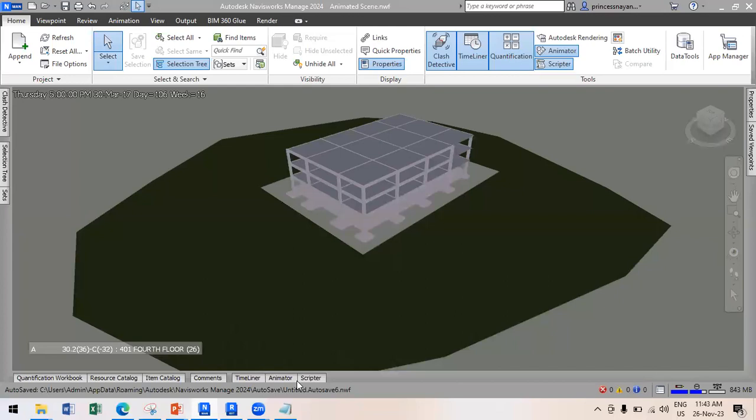The advantage is, imagine if you do any modification further, you can do one more quantification and you can see the previous and existing. It's very simple. There is a method, but first you should understand the tool. We have to create project parameters, shared parameters, because sometimes floor-wise we have to give, sometimes part-wise. All those things we can do here. Array bar is there.